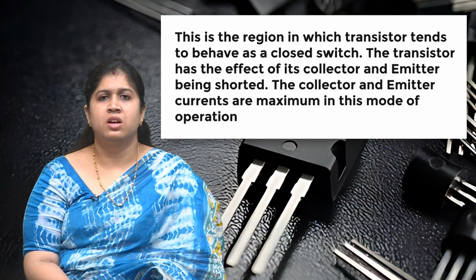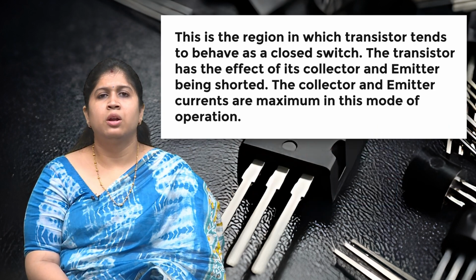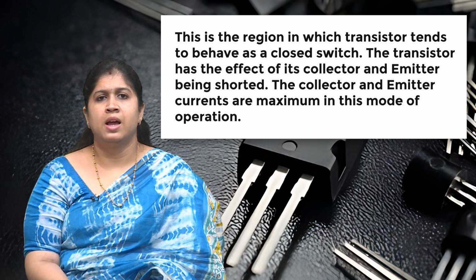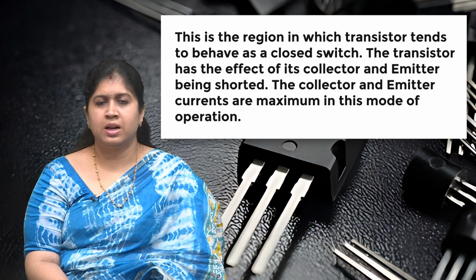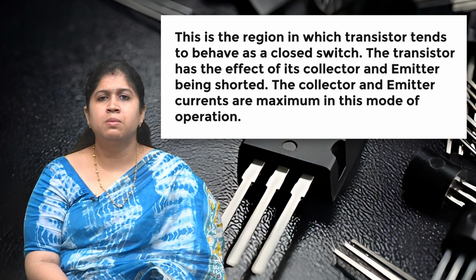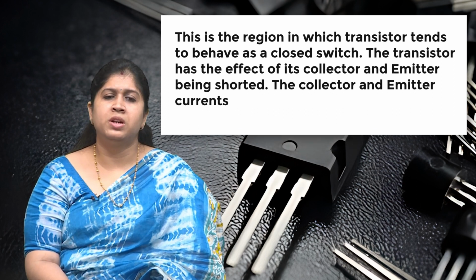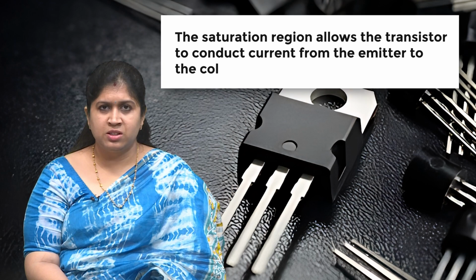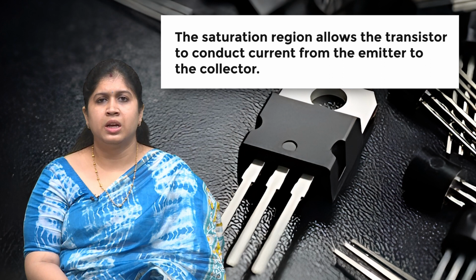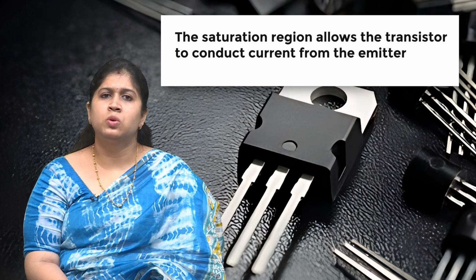This is the region in which the transistor tends to behave as a closed switch. The transistor has the effect of collector and emitter being shorted. The collector and emitter currents are maximum in this mode of operation. The saturation region allows the transistor to conduct current from the emitter to the collector.